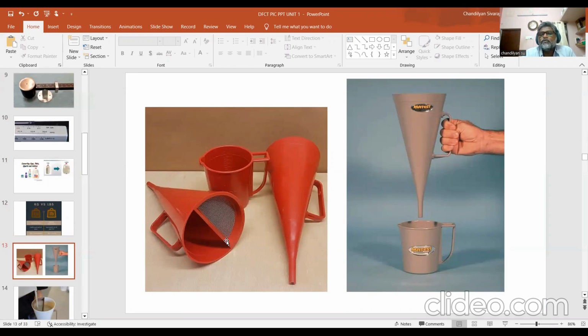One end is kept open, and one end is for removing the excessive solids. You will pour it here, it will get in, and you will note down the time. You will work out the viscosity. But the standard is universal, whichever country, laboratory or college you go to, it is going to have the standard dimensions. The diameter, the cone size, the orifice size, the least tapering sections, all are defined according to the American Petroleum Institute and ASTM, the American Society for Testing and Materials.